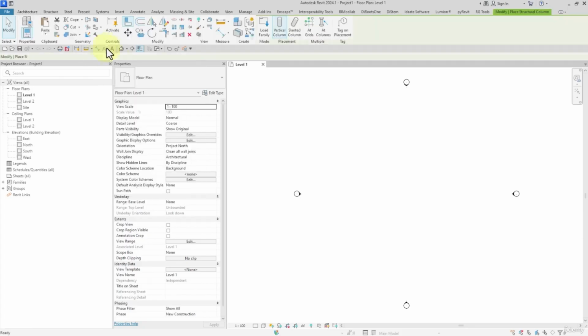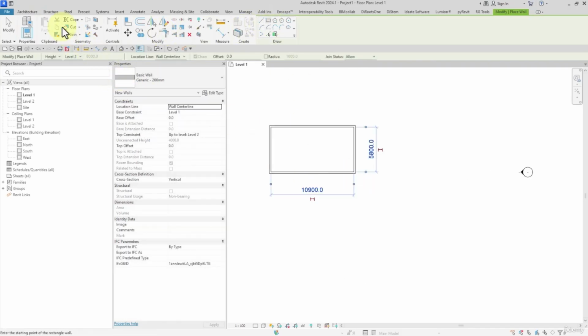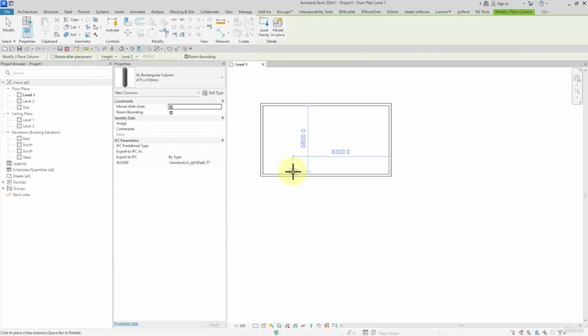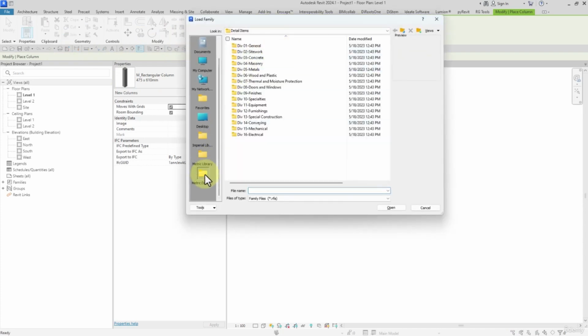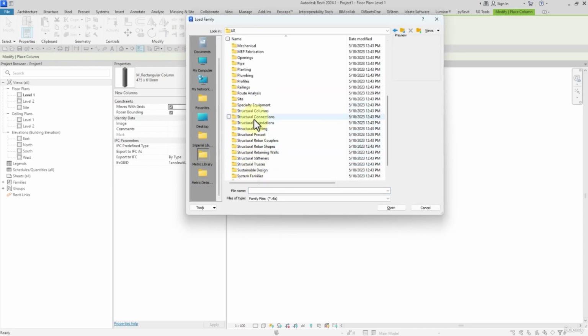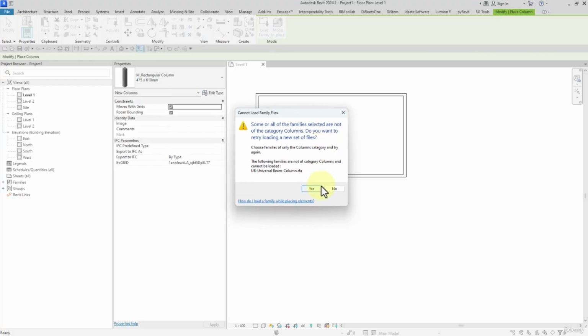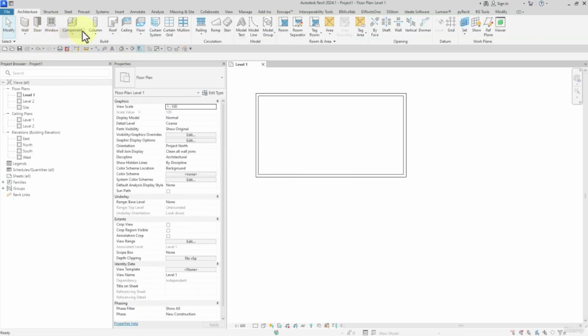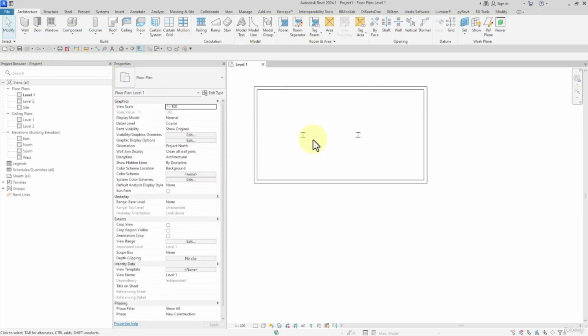For example, where we have added or used structural columns, we use architectural columns to design these structural columns and make them more decorative. For instance, suppose that here we got a space, watch this part, like this way, and then if I select the structural column, metal columns, steel columns actually, then I want to add this into the project. For example, this type, the dimensions are not important for us right now. Structural, like this way, height, level 2, and then I add these.